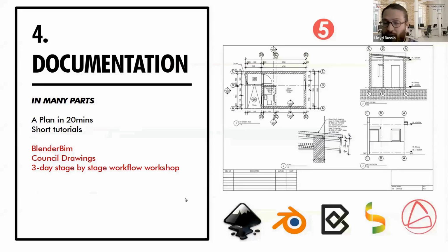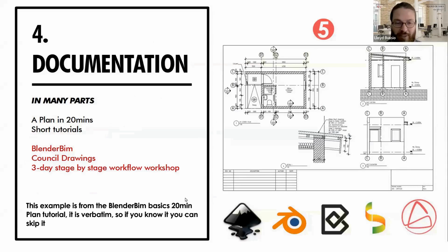I'm just going to do a short plan using BlenderBim. And then here I was mentioning that in the 3-day workshop, we are going to do each stage. So I will do to a level of council drawings. And we're just going to do some documentation. I'm going to show you how to do some very basic modeling in BlenderBim and how to do that same kind of modeling in native Blender, and then how we can get some 2D drawings out of it, some very simple ones. It's not a full tutorial, but it's definitely everything you need to get going.